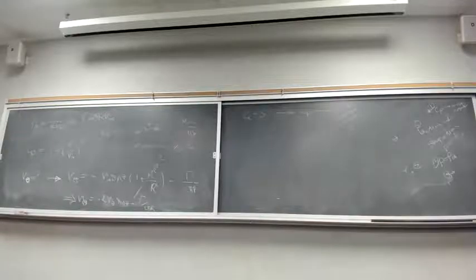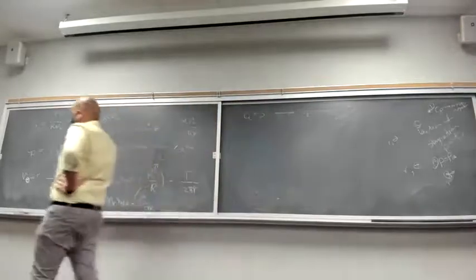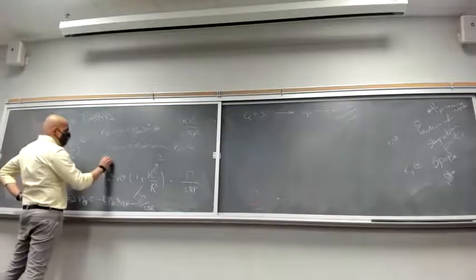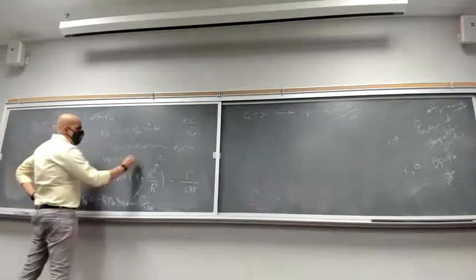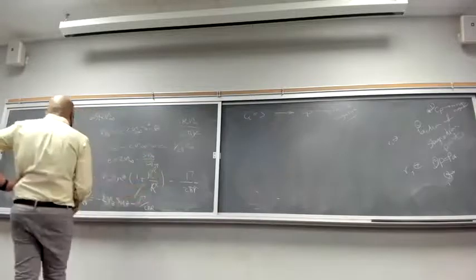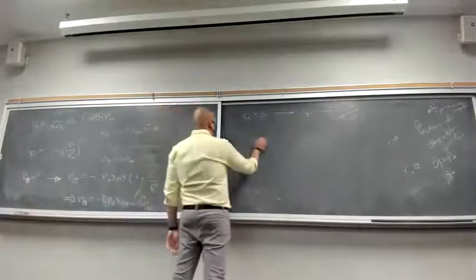What can you say about theta? Zero? Theta is going to be at the top and bottom. So pi over 2, right? That will be the location of your most negative, essentially at the bottom. So at negative pi over 2. So we're going to get negative 1. V theta is going to be 2 V infinity minus 5 V infinity over 2 pi. Okay, plug that in to get the location of the most negative.